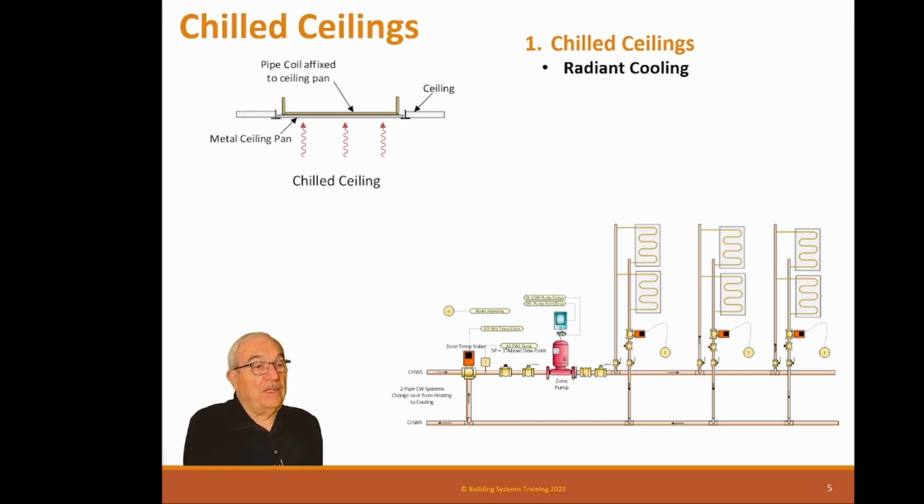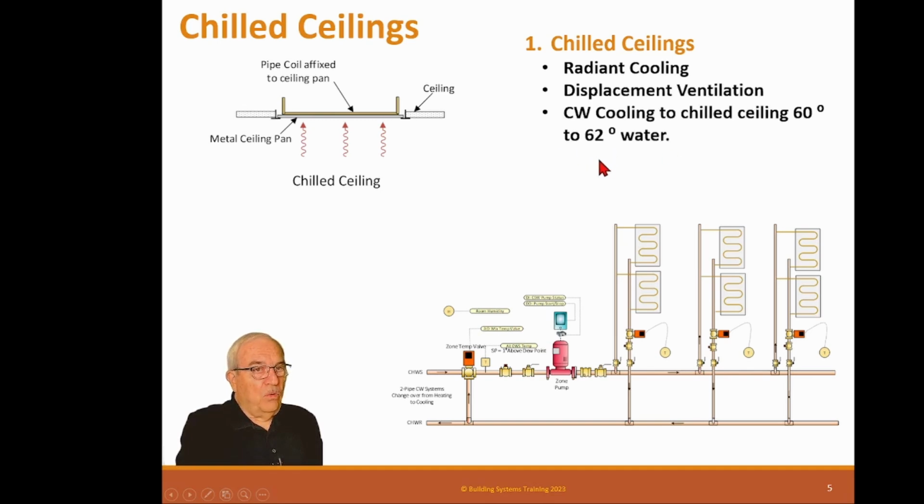It's very comfortable. The radiant cooling effect of taking the heat and radiating it up to a cold plate is very, very comfortable. So these have a lot of advantages: low energy, very comfortable, and of course, very quiet. People got them and really liked them, but they're just so different that people kind of reject them. So what's happened is these basically have gone away in favor of chill beams, because this is the predecessor to chill beams, and we'll talk about that in a second.